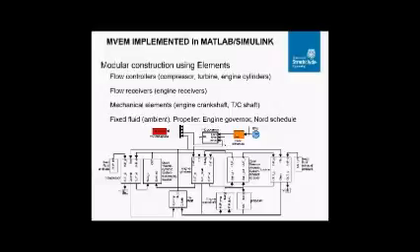We have the flow receivers, the engine receivers, and elements like the engine crankshaft and the turbocharger shaft. We have a fixed pitch propeller, which is connected with the engine crankshaft without a gearbox on a two-stroke engine and with a gearbox in a four-stroke engine.